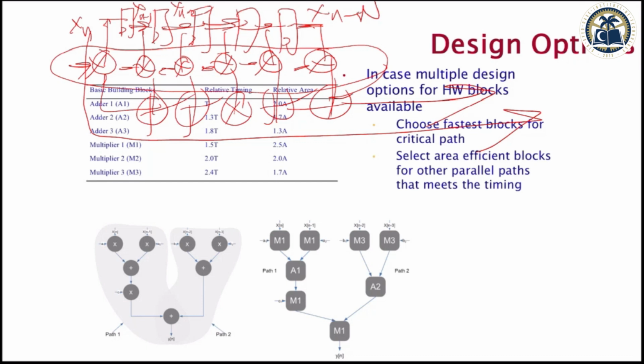Let's say the length of this is 5,000 previous values, and you're doing it on wireline, 5,000 previous values of the stock that you are using to predict a new value. So 5,000 adders delay will be very, very slow. Why? Because you are not using these registers to break your critical path somehow. So sometimes these registers are valuable, which you can move inside your circuit. Systematically you can move all your algorithmic registers. This is very interesting. All your algorithmic registers can be moved inside your circuit.